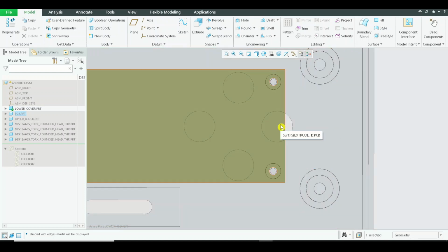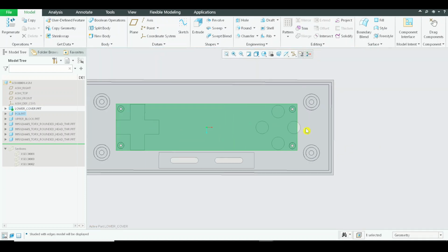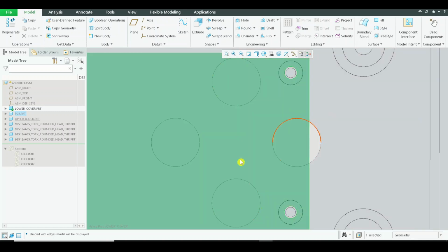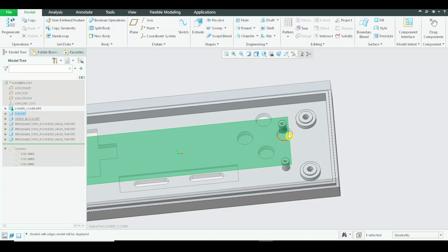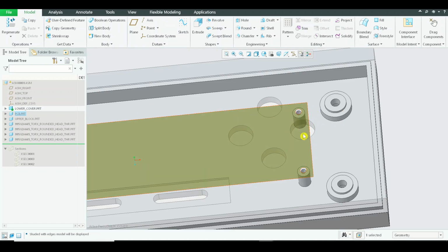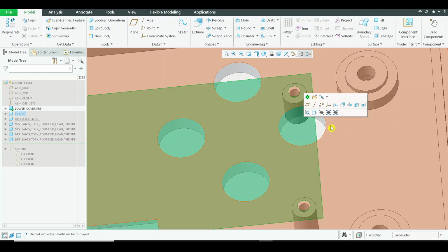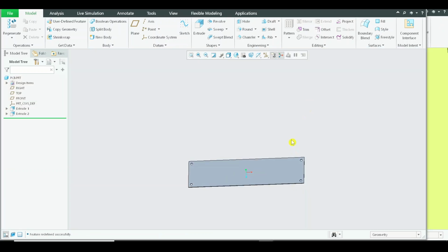So what we need to do is extend the PCB board slightly to the right side so that it covers the entire circle of this thing. Now there are two options for us. We can either reposition the bosses slightly inward, or we can modify the shape of the PCB board by extending it outward. I will be basically expanding the shape of the PCB board.